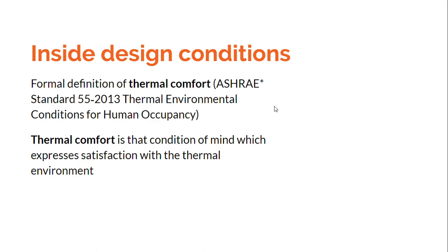Inside design conditions are defined by ASHRAE, American Society for Heating, Refrigeration and Air Conditioning Engineers. And there is a standard to it. You can Google this standard, standard 55 2013. According to this ASHRAE, the inside design conditions are to be selected on the basis of thermal comfort for comfort air conditioning applications.